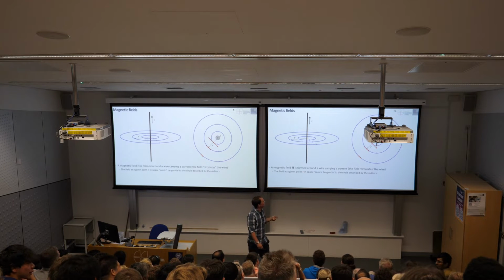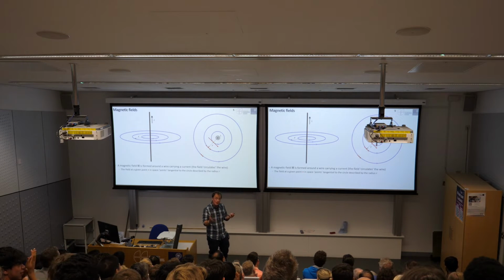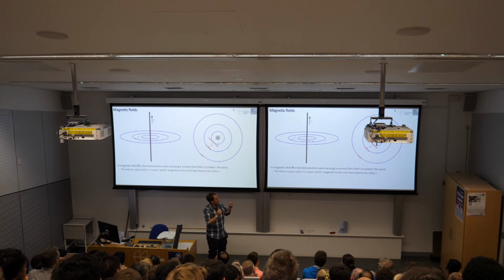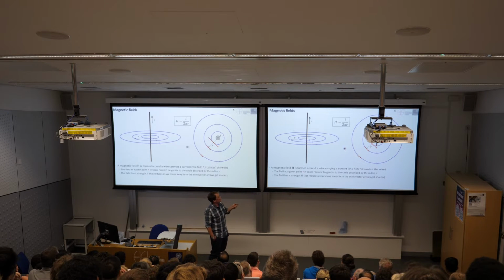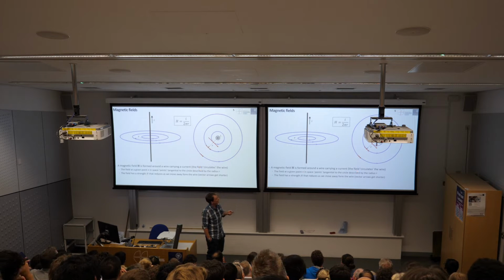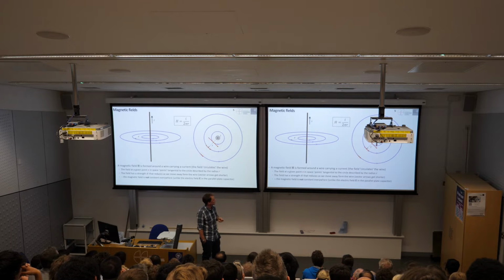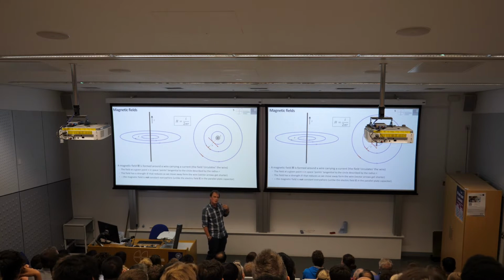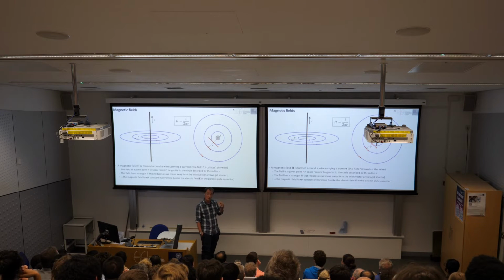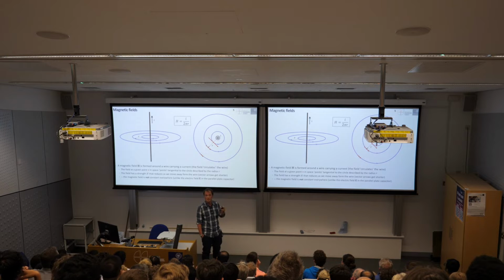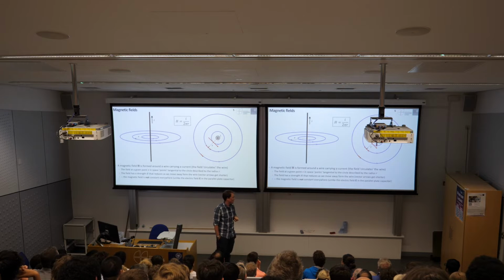And it's circulating, so it doesn't point in the same direction everywhere. It points tangential to these circles that occur around this wire. So the equation for the strength of the magnetic field, that is the length of the arrows, is just I over 2 pi r, where I is the current flowing through the wire. So it's really important, and this would make more sense if you'd already been to my lectures on capacitors, where we see that the field strength in most capacitor structures is constant everywhere, and this makes the problems easy to solve. That's not true for most magnetic problems.